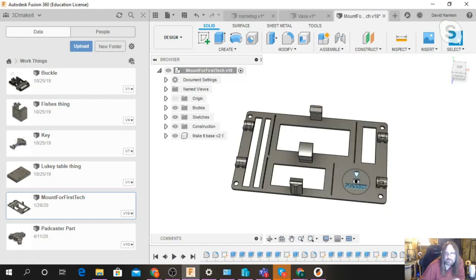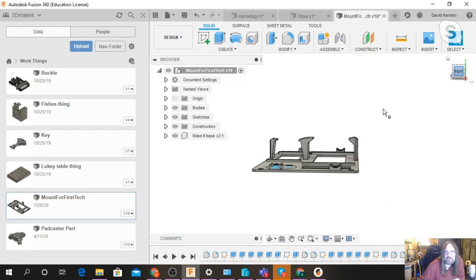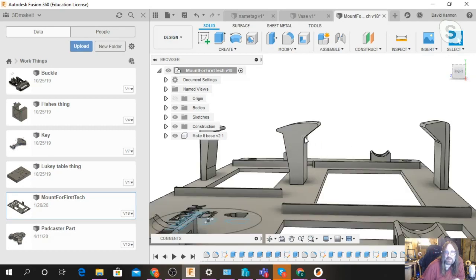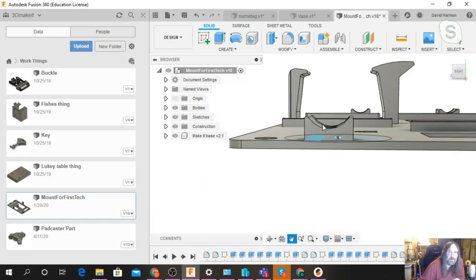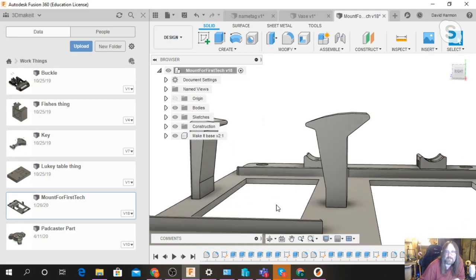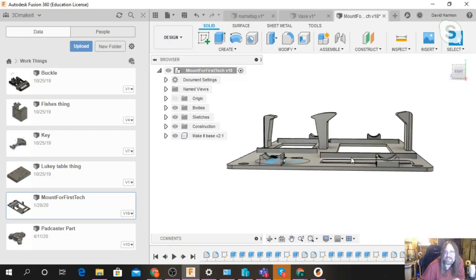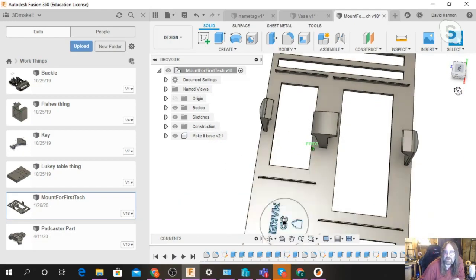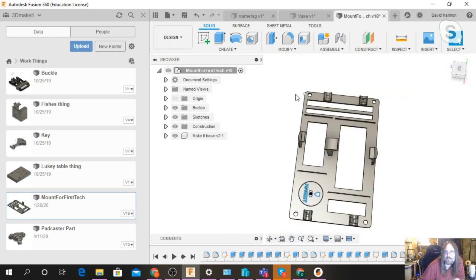So just remember that if you're building an angle, let me show you an example here. See on our posts, it comes up and out. Your 3D printer will be able to print this without support. And actually, you can print this whole object without support. That was one of the fun challenges we had. And you can see we took wings off the thing, so now it's a nice rectangle with some fillets on the corner. And yeah, it's a great project.